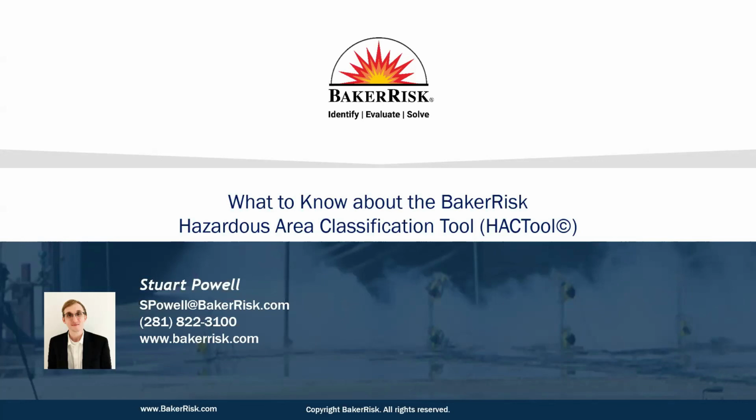Right, so the question being, can HACTool handle the dust side of things? Right now, HACTool is capable of flammable and combustible dusts and liquids, and we're working on the development of the dust side of things. That was the NFPA 499 that was referenced as a future development. You may have seen some of the underlying workings in the software. You do have the ability to select a class 2 area, which indicates a dust hazard. But the functionality to overlay a dust area, to calculate a dust area, and check for electrical compliance is not in the software as of today, but that is the first item we're looking at adding on that future improvements list.